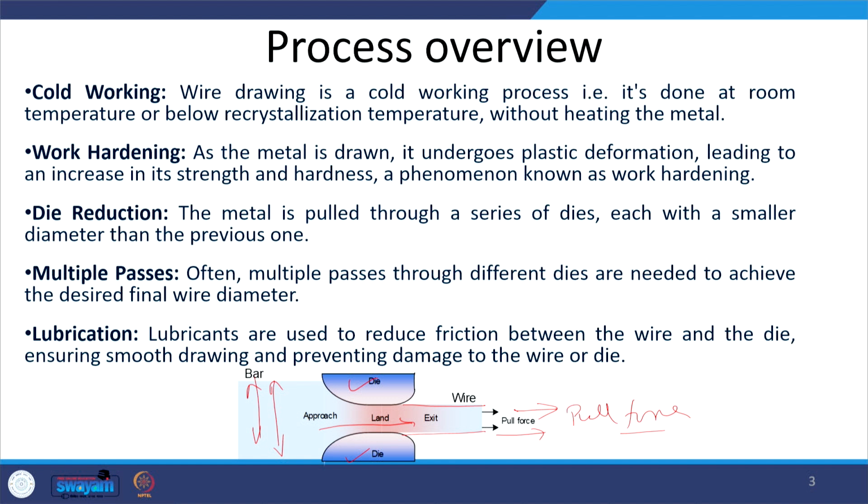While in the case of extrusion, we have seen that we apply a push force, or compressive force, here we apply the tensile force. Here the design of the die plays a very crucial role in ensuring that the flow of material takes place when the tensile force is applied, so that the diameter is reduced without the possibility of necking or fracturing.